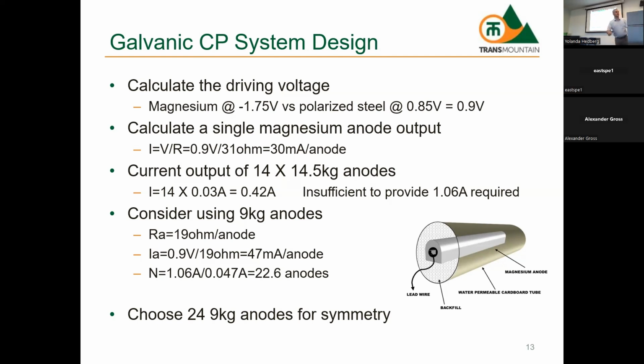Good. Okay, I think we're done with galvanic. So just to finish this one, 24 anodes, 3 tanks. You would literally just space them out so that they can be all around the structure and protect every little part. Because a lot of times the tanks will be close together, where you're going to want to have the anodes in between them and protect the whole structure.